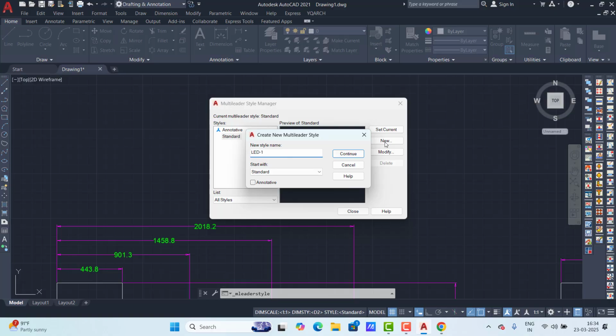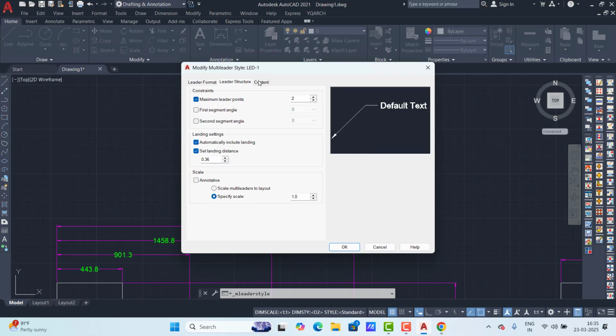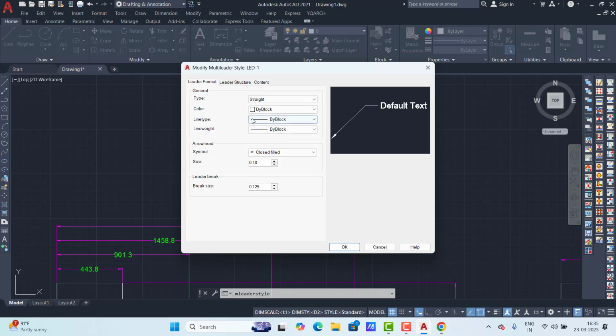See, the text does not come, because in this setting the leader structure is completed in 3 steps. So first click here, second click here. Now we go to the third click. If you want to go horizontal, you can activate auto and just click. So when you click 3 times, now the text comes. You type the text this way. This way it can be presented.